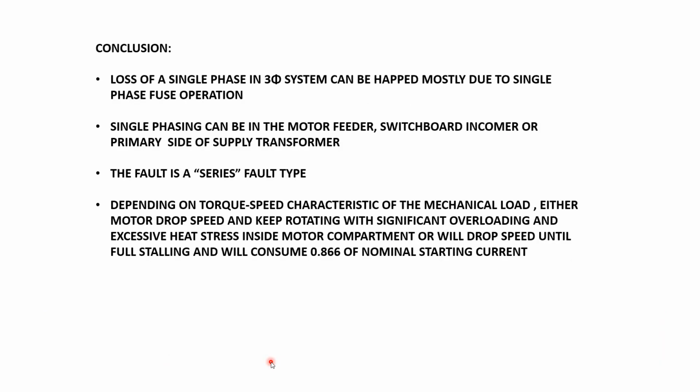So we're going to the conclusion. Loss of a single phase in a three-phase system can happen mostly due to single phase fuse operation. Single phasing can be in the motor feeder, switchboard, incomer, or primary side of the supply transformer. We see that single phasing at different points has different symptoms. The fault is a series fault type, so within symmetrical components, we are investigating a series fault.